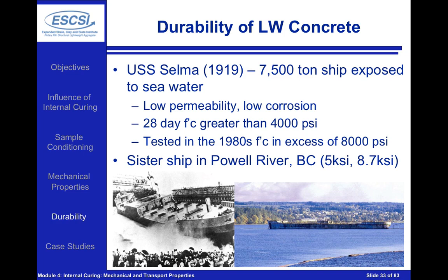Now, the final thing I really want to mention on that is having a lower modulus can actually be beneficial when the concrete is restrained and when we're worrying about cracking, because lower stresses are going to be building up inside of the system.